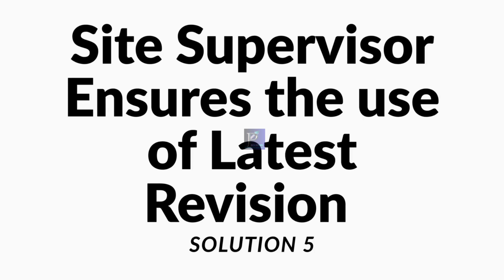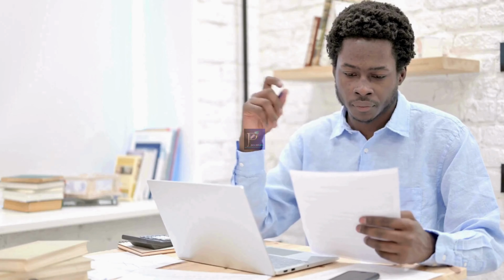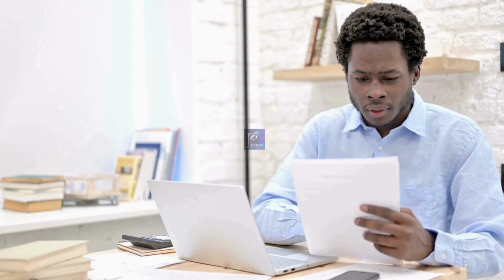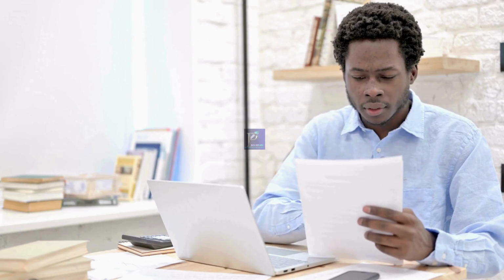So before starting any work, the site supervisor must verify drawing status and confirm the current revision he and his team are working on. This is a very important point.